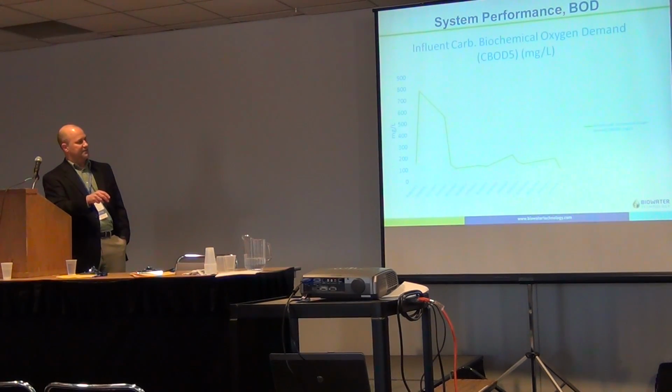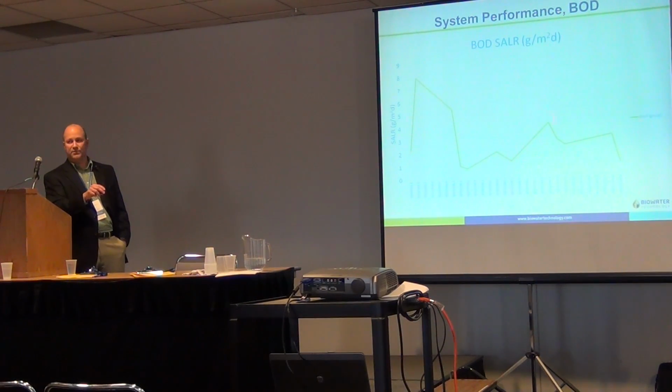It's very similar to the milligrams per liter, but when we take the flow coming in, we do get some bump ups when the school's coming around. So from a design standpoint, looking at milligrams per liter versus surface area loading rate, it's actually a little bit closer than it would first appear, but still very wide conditions that it has to meet.